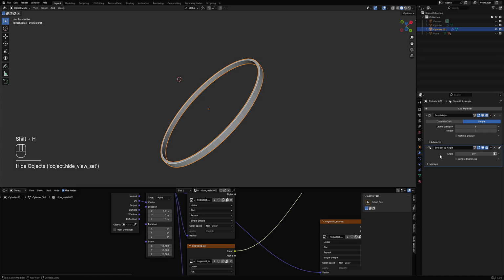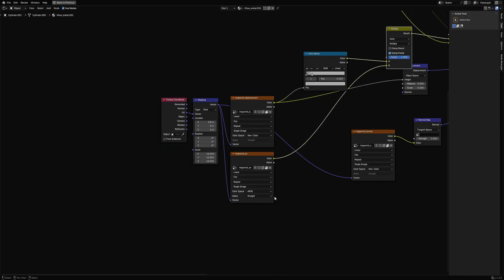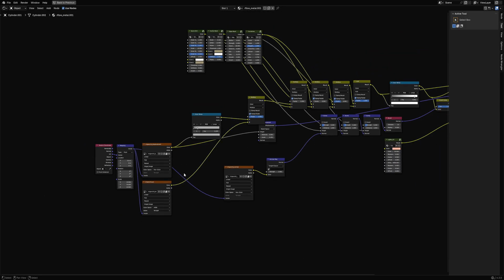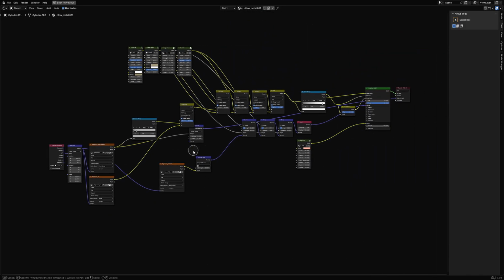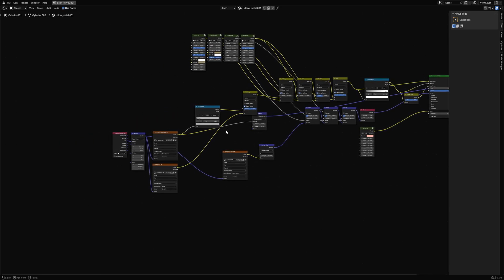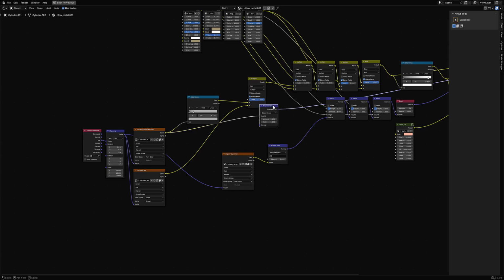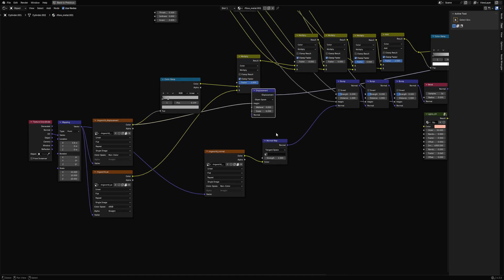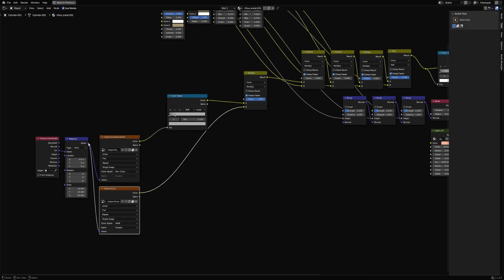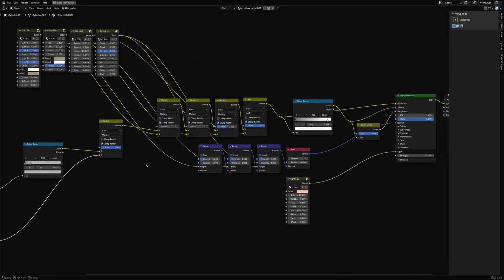And then subdivision, small by angle. We're going to delete most of the effects we did because we're basically using the displacement. So we'll delete this, the displacement modifier, the normal. We can still keep this just for texture effect on the surface.